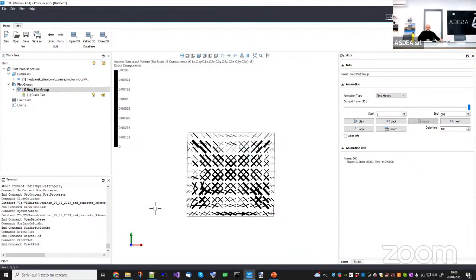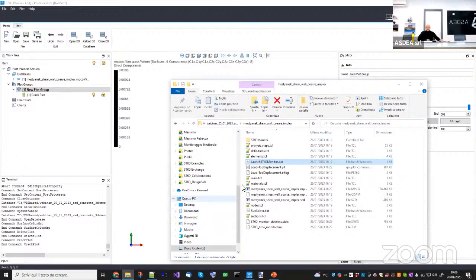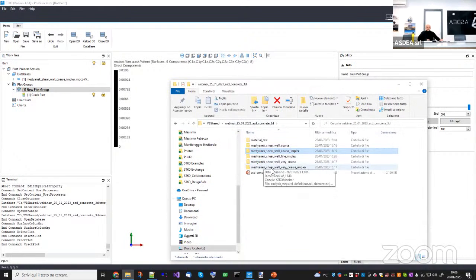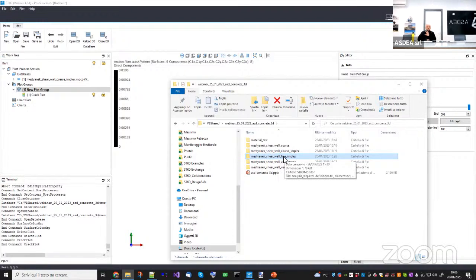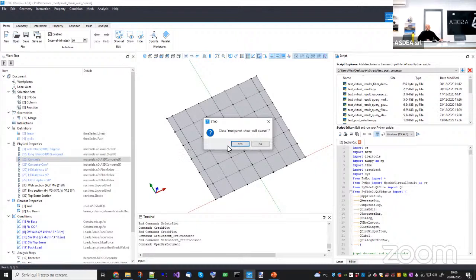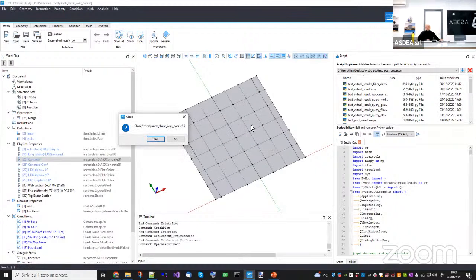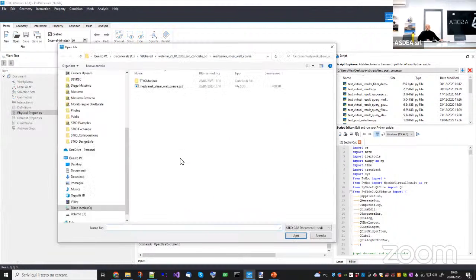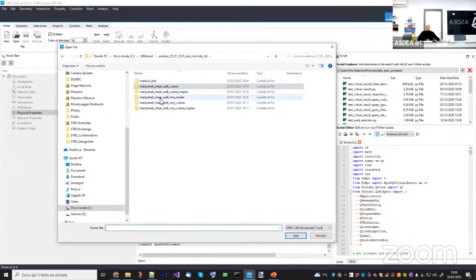So it's much better to visualize. Finally, you can find an extra example here, which is the wall fine IMPL-EX. In this case, I only use the implex algorithm just for reasons of time. So you will see the mesh is quite fine. But what you can get now is that basically this kind of mesh is already very good for this kind of analysis. But if you want to improve the solution, you can go with a finer mesh,